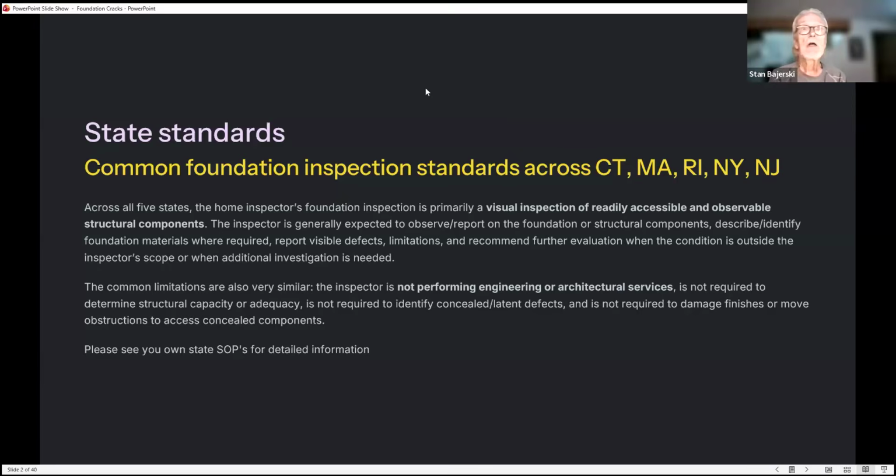readily accessible and observable structural components. The inspector is generally expected to observe and report on the foundation or structural components, describe and identify foundation material where required, report the visible defects, limitations, and recommend further evaluation when the condition is outside of the inspector's scope or when additional investigation is needed.